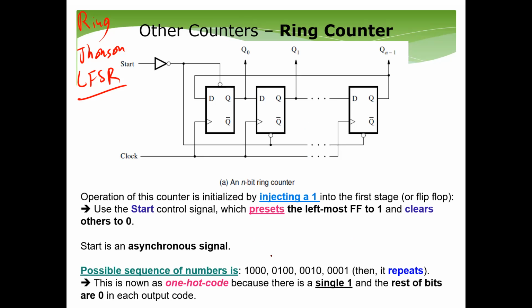The ring counter will start at a state. In a 4-bit ring counter, you start at either 1000 or 0001, depending on whether you are shifting right or left. Next clock cycle, this goes into 0100. You are basically shifting the 1 along to the last bit. The difference between a shift register and this counter is that in a shift register, after this state you should get all zeros. But here, no: from this state you move back to the first state.